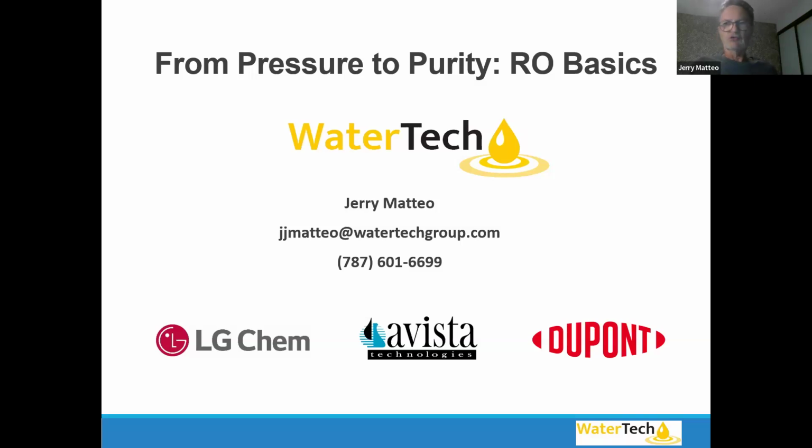And everything's solvable. You can solve most of the components in the water chemically. You use a good anti-scalant and you profile that: what anti-scalant will take care of these things in my water? But you need good pre-treatment. The beach well is typically better on turbidity, so you're more forgiving for your pre-treatment system. That's probably why they went that way. To me, it's hard to think what I'd rather work with. Maybe I'd rather work with a beach well, but because I know the chemistry, you're probably going to need more chemistry on a beach well, depending on what other dissolved solids are in there, but it's more forgiving on turbidity.